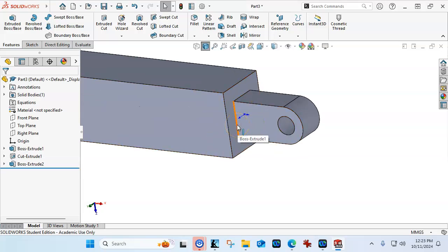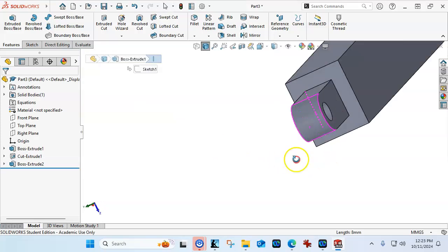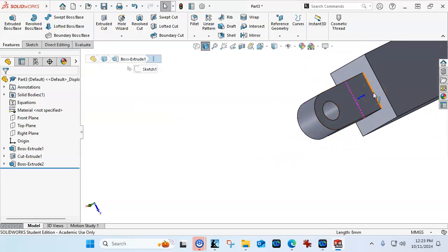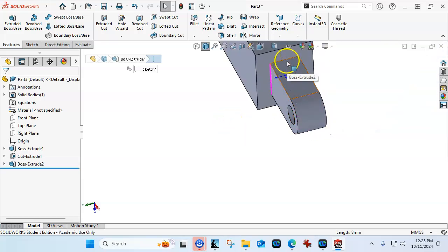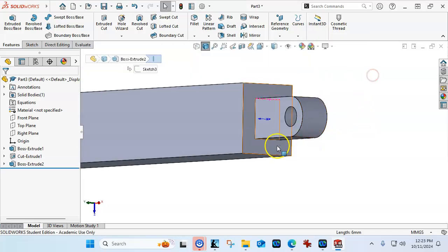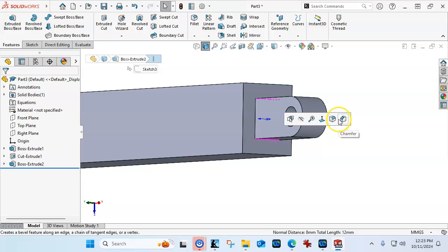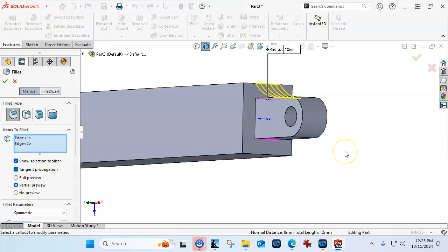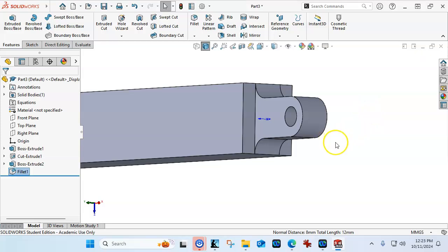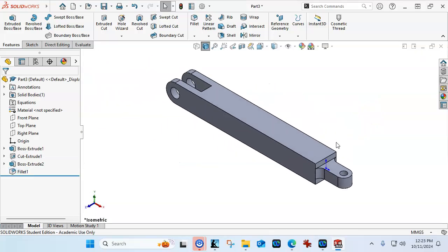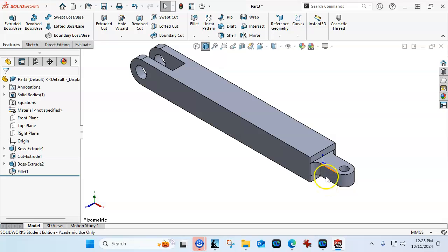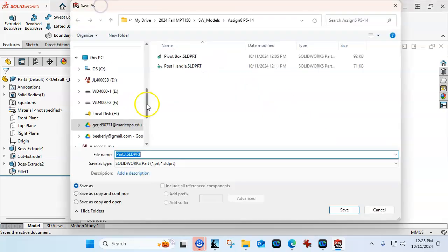So my caution for having these radius geometries, and let's see, that is on this side, and this side is, it does help to protect against a stress riser. The problem is machining it is not always going to be very easy. So if it increases the cost of the part, you'll want to rethink or make sure that that is a desired outcome. All right, so we'll go ahead and save this as the link.